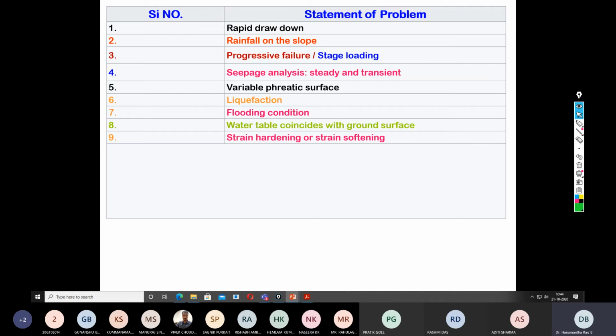In the dynamic condition, there is a variation in the pore water pressure. So there is an increase or decrease in the excess pore water pressure, which has an obvious effect on the factor of safety. So this leads to variability in the factor of safety. Now the first thing is that when the factor of safety is varying, does the variation take you to the least factor of safety where you are going to encounter the failure?